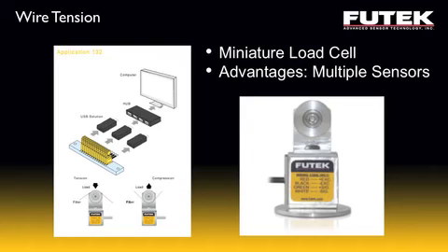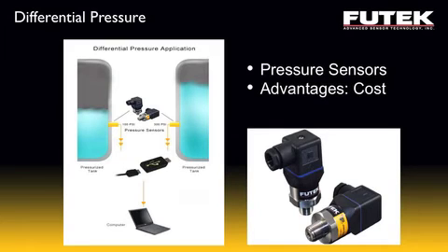Now, we've talked a little bit about load cell applications, so I'll switch here and provide an example of a pressure sensor. Here, we're measuring differential pressure, and we're using 2 different pressure sensors to measure 2 different media. We use the software to subtract the measurement or show the difference between the 2 chemicals. And again, this has a very broad reach for anyone interested in mixing materials where pressure affects how much fluid is dispensed. So you'll find this again to be a universal or dynamic application.